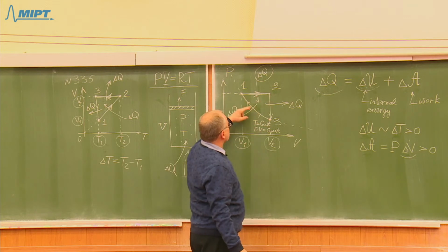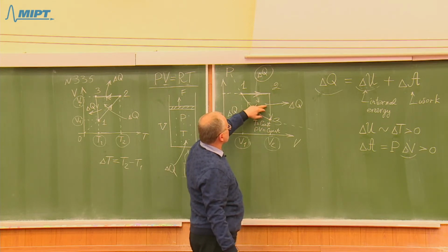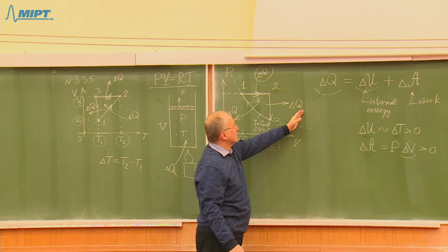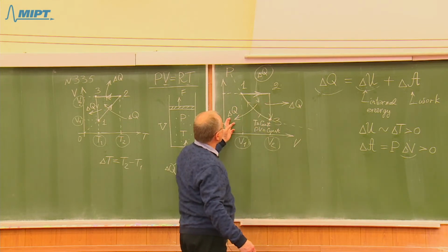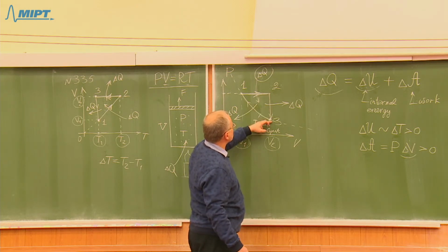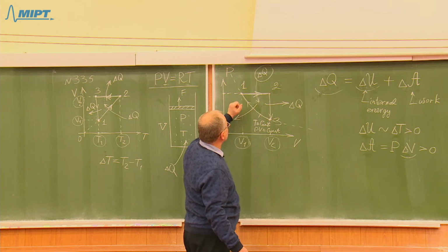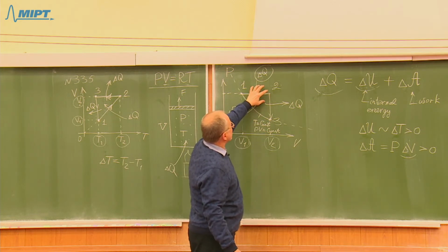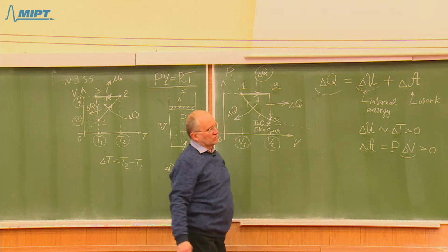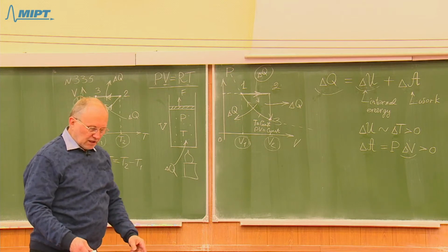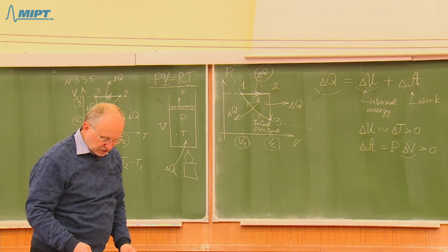During the remaining two sections, the heat energy is transferred from the gas and given to the outside bodies. The gas releases heat energy during processes 2-3 and 3-1. The only process when the gas receives heat energy is 1-2. In all other sections, the gas loses heat energy.